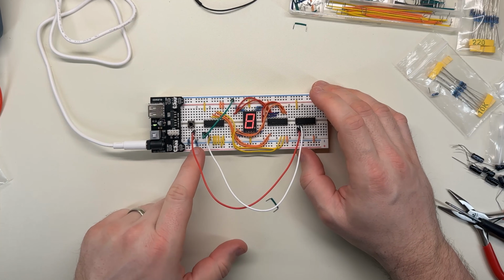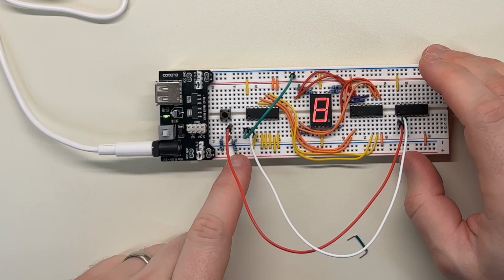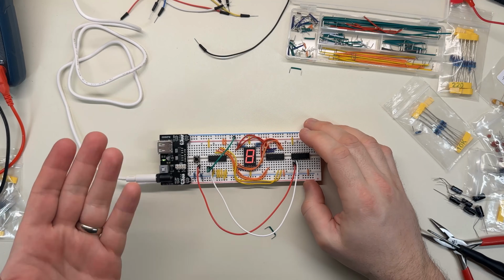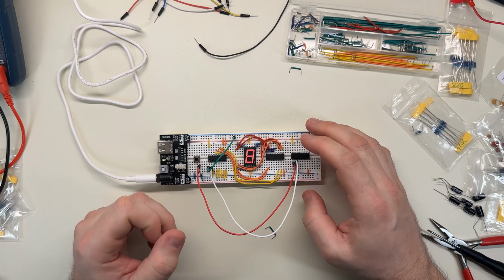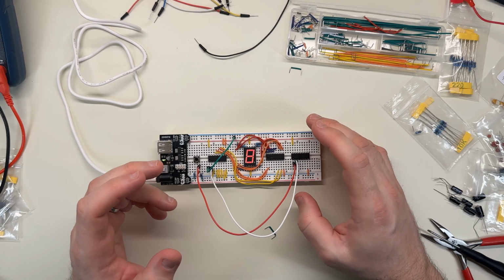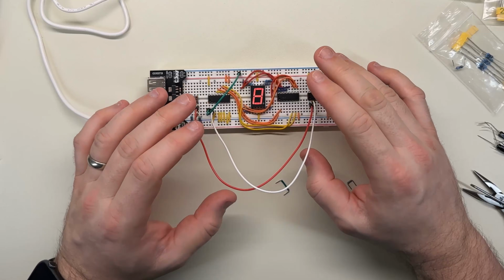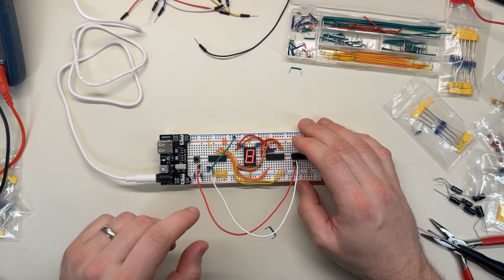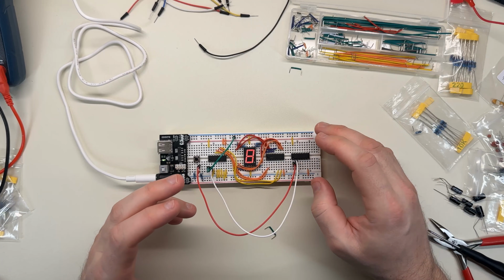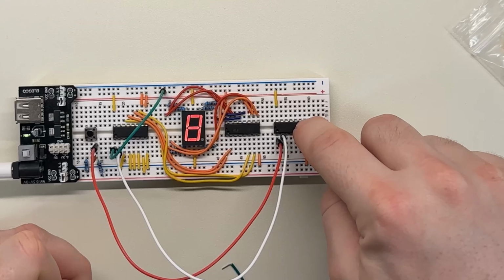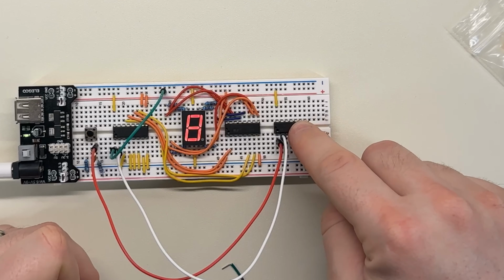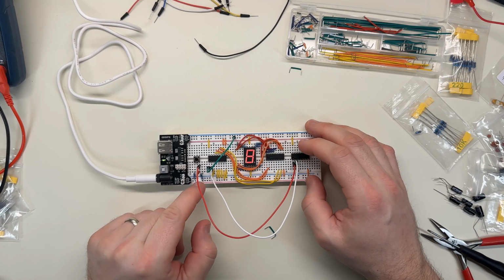So then it occurred to me, how is this resistor capacitor chosen? Well, it turns out with RC circuits, you can simply multiply the capacitance by the resistance, and it gives you a time in seconds. And that time, I think, is roughly 60%. It means the capacitor is roughly 60% full in that amount of time. That coincides pretty nicely with the voltage level required for a true on this chip. But that means you can adjust the time simply by putting a bigger capacitor in here.